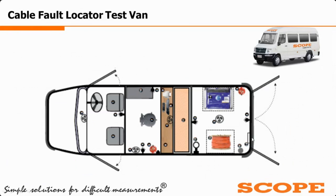You have to close this door and take the cables out from this cable duct, so that unauthorized personnel cannot enter the high voltage area. If this door is not closed, the high voltage section will not turn on. These are the various safety features provided in this van. This is all about the cable fault locator test van offered by Scope.